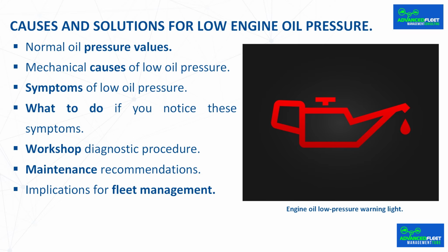Implications for fleet management. The main consequence of low oil pressure is serious engine damage, which is costly and results in the vehicle being out of service. Low oil pressure is one of the most critical failures in an internal combustion engine. Knowing the pressure values in bars, identifying the mechanical causes, and performing a systematic diagnosis are essential to avoiding costly and unnecessary repairs, which can range from replacing the oil pump to a complete engine overhaul.